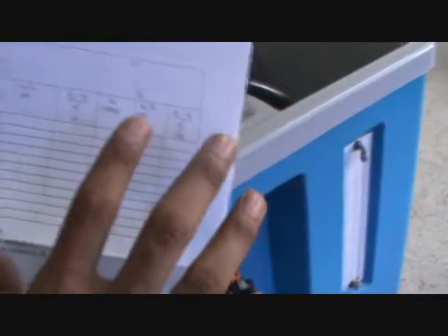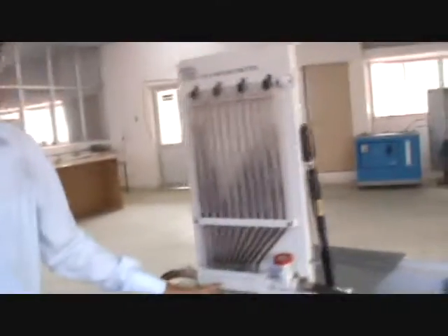As you know from the continuity equation, discharge is equal to area into velocity. The discharge can be calculated from before, that is the actual value of discharge, and you know the cross section area at throat section 2. So that discharge divided by the cross section area gives you the velocity at throat section 2, that is U2. So you will get this factor, Hn minus H1 divided by U2 squared by 2G. Just plot this factor, the non-dimensional pressure drop, versus the length of the venturimeter, and you will get the pressure distribution.